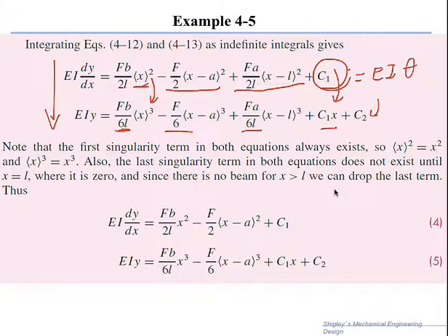And note that if we have the singularity function with x greater than 0, then you might as well make what is in between the angular brackets a normal polynomial. Everything in between brackets for x greater than 0 should be a normal polynomial.